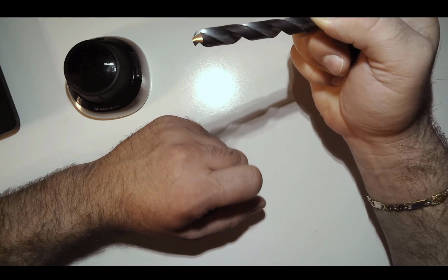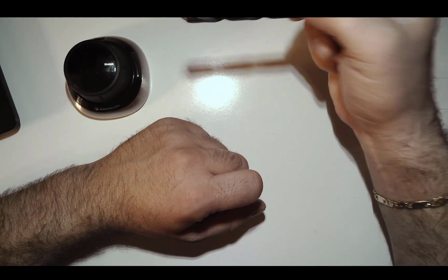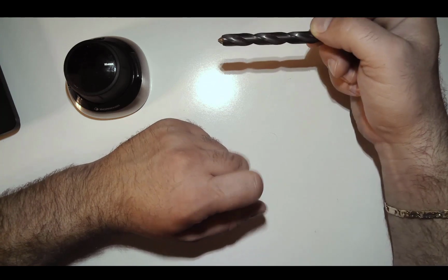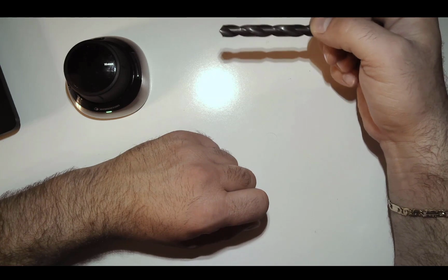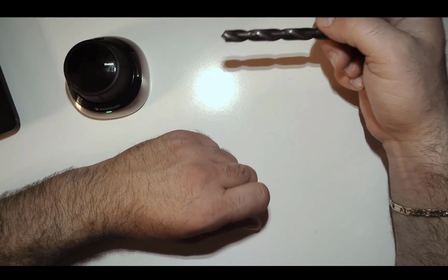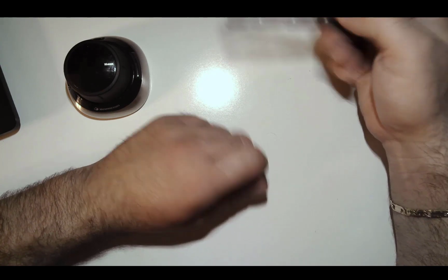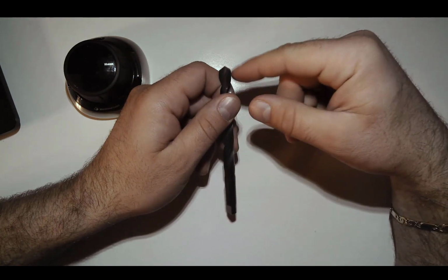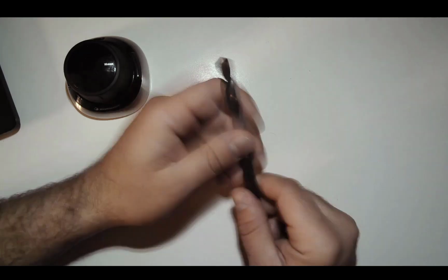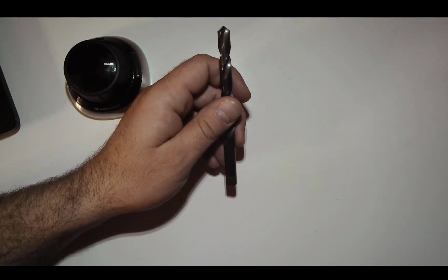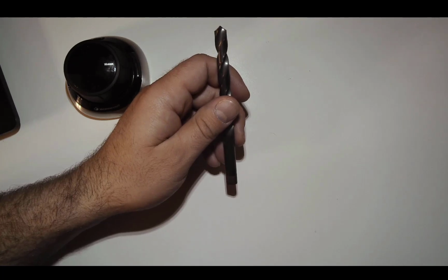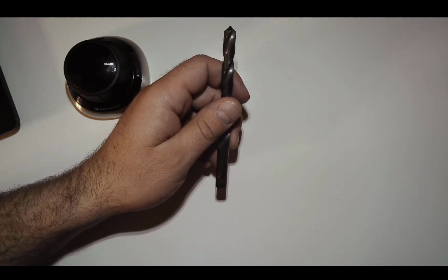So when this is drilling into material, once I plunge it in the specified depth, it's going to leave a conical impression at the bottom of the hole. These are typical angles that you can find specs on in the Machinery's Handbook.